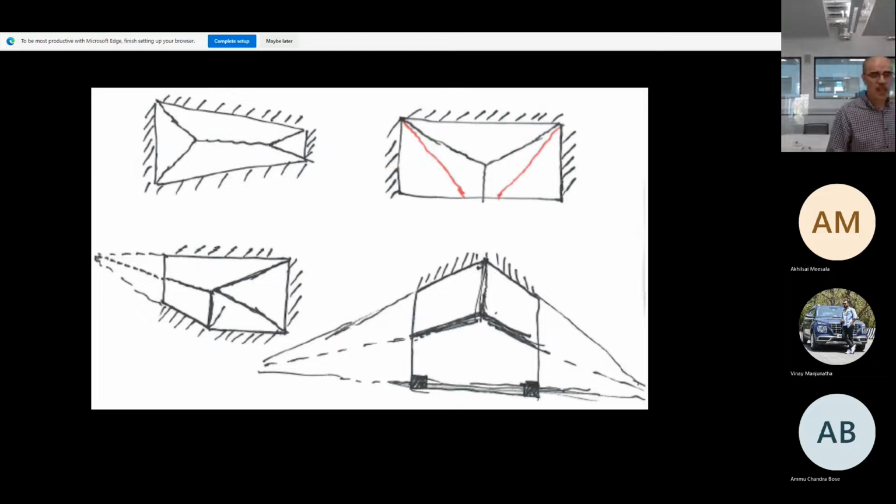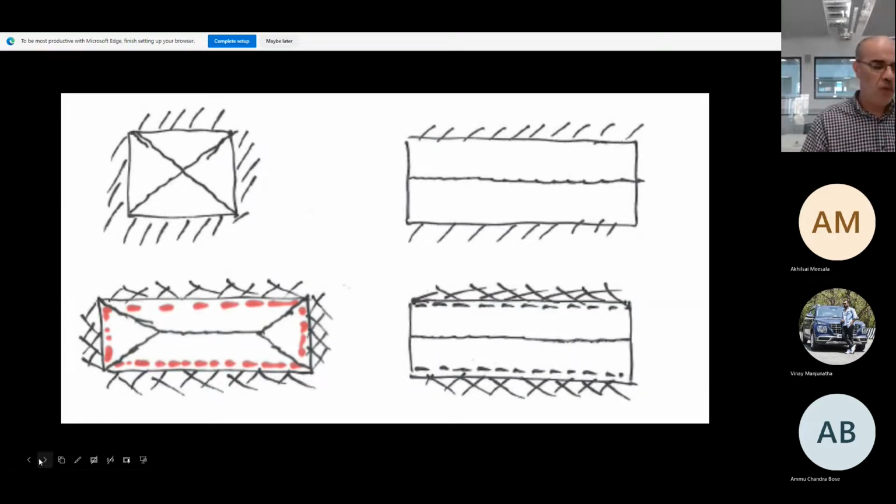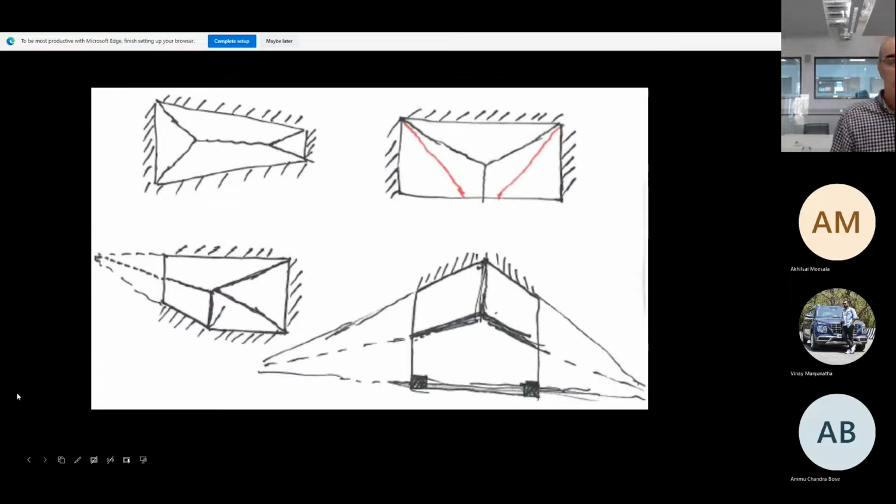You just have to follow the rules, which is that the yield line starts at the maximum points of curvature and then extends to the intersection where the axes of rotation are. Clear? I mean, what I've given you here are the most common ones that we are going to encounter, and depending on how much time we have, I will be looking at an example of each one, just to show you how we analyze slabs with different boundary conditions. Okay. Any questions? Is that clear? Okay.